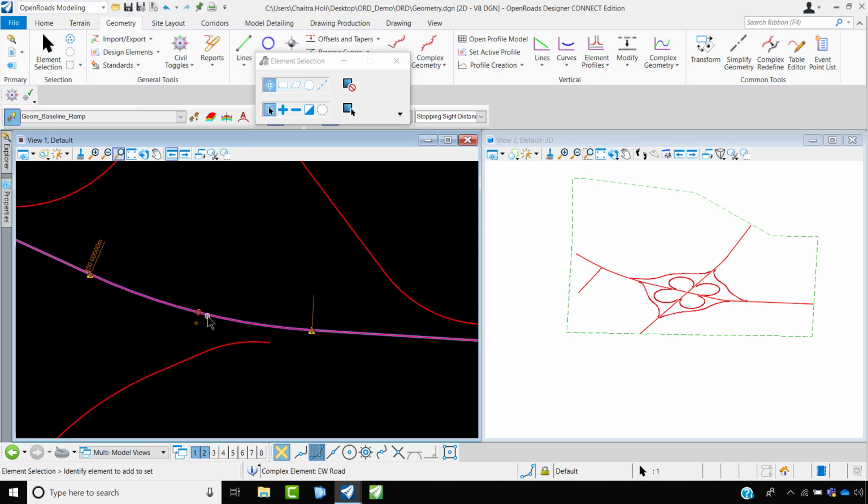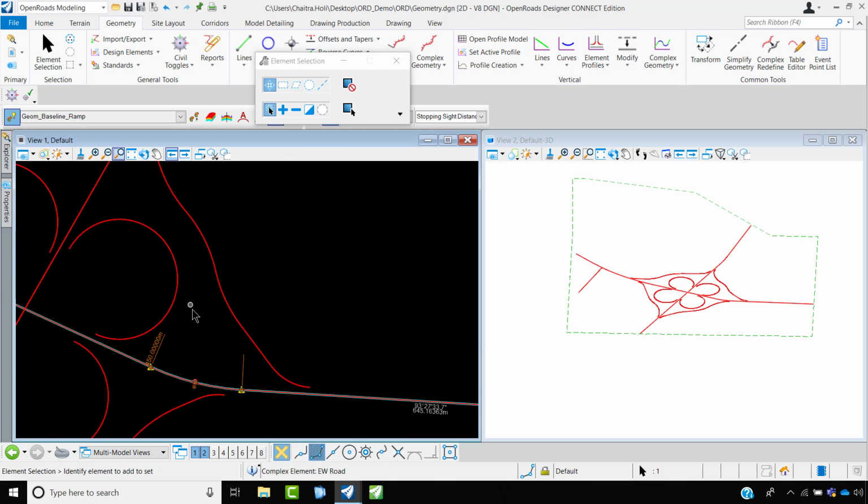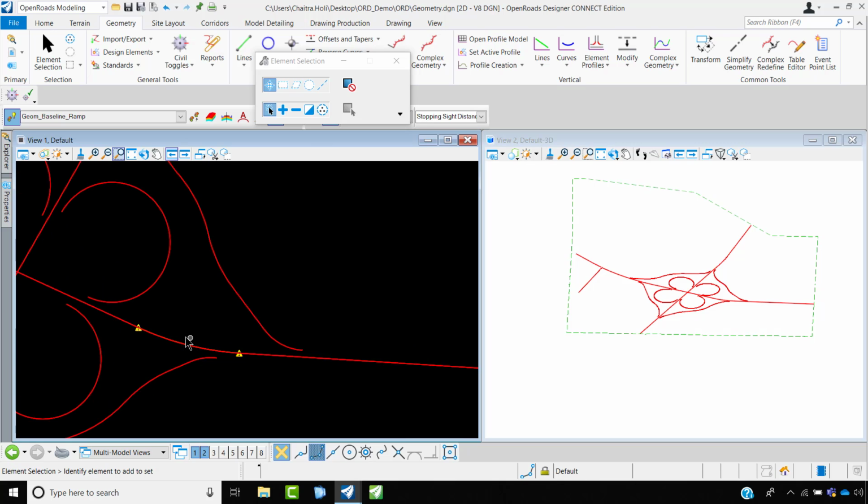So you could directly click on the alignment, click on that value, and directly text edit over here, and say I give it as 500. Now you don't see that error sign over here.